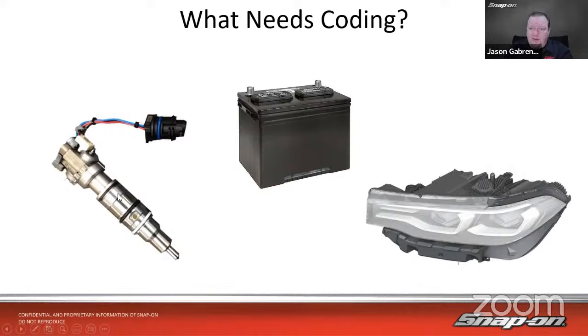And oftentimes it's to calculate the flow rate, to tell the computer what the flow rate needs to be for this particular injector, because every injector is going to be built a little bit different. Every injector is going to be built to flow a little bit different. So I need to tell the computer, hey, this one flows at XYZ rate versus the one that may have been in there before flows at ZYX rate. So you need to go and program that in. That's very common, especially on direct injection and diesel vehicles. But very, very common out there for injectors.